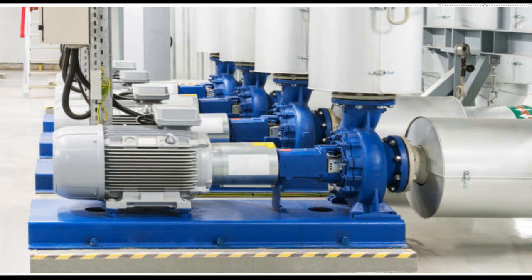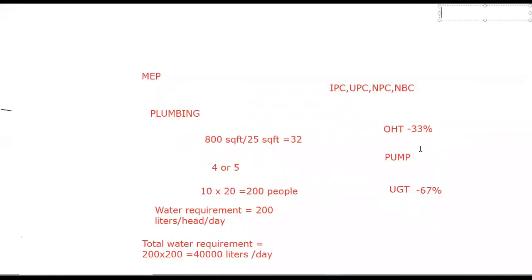See, if he is suggesting that wrongly, for example, if the actual requirement is 5 HP, then if he is suggesting 10 HP, then in order to purchase 10 HP, the cost will be more, isn't it? So that is one thing. Our system should be cost effective also. Same way, if the actual case is 5 HP, then if he is suggesting a 2 HP motor, then what will the client do? Based on the plumbing design engineer's suggestion only, he will purchase and install. Then what happens? Always the pump has to run. Pump running hours will be more, because they have purchased only 2 HP instead of our 5 HP. So in order to fulfill this requirement, always the pump has to run. Our electricity bill will be more. So many things are there in practical application. Always there is an engineering concept, but we people are not aware. In this particular industry I am talking about.